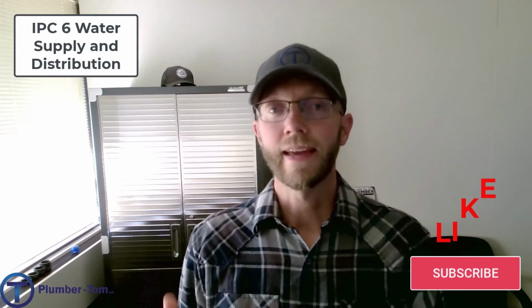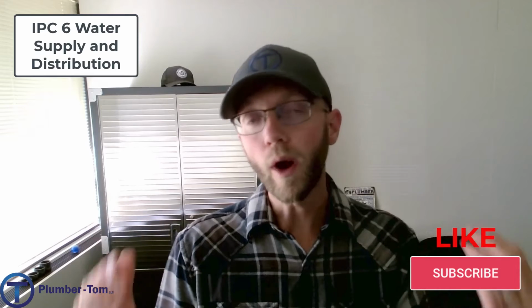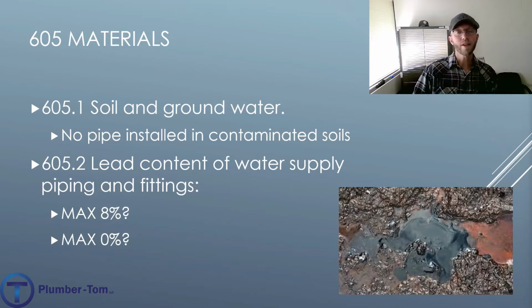Let's check it out. In 605, we look at materials, joints, and connections. We're talking about what kind of pipes we can use and how we put those together. 605.1 talks about soil and groundwater and helps us understand that if a pipe is put into contaminated soil, let's say it has chemicals in it, that could very adversely affect the pipe. I mean, it could contaminate the water. So we have to be conscious and careful of what the ground is like that we're putting these pipes into, and obviously not install them in any contaminated soils.